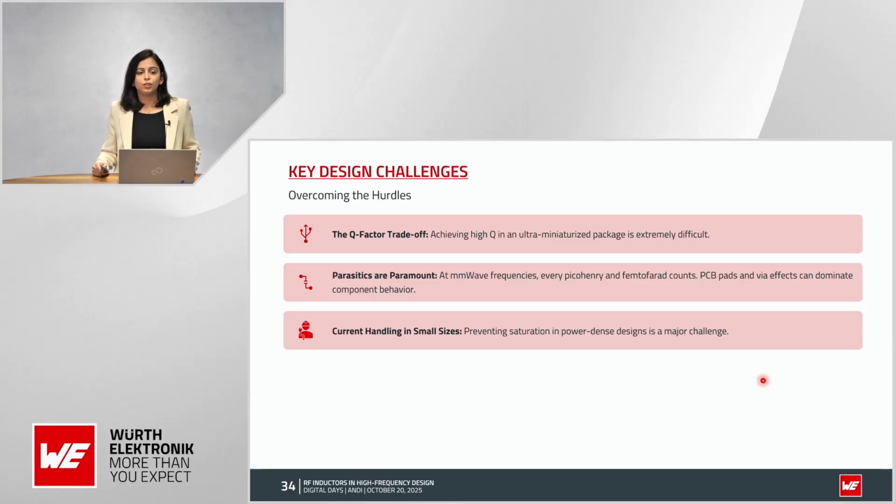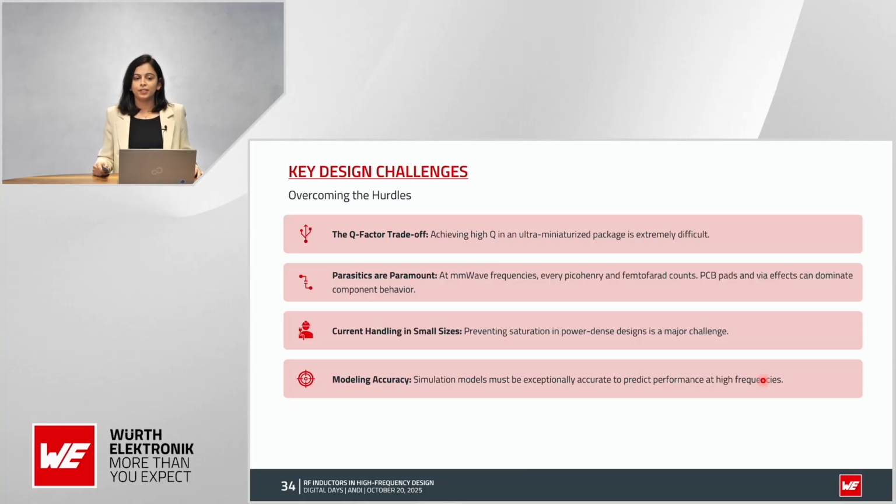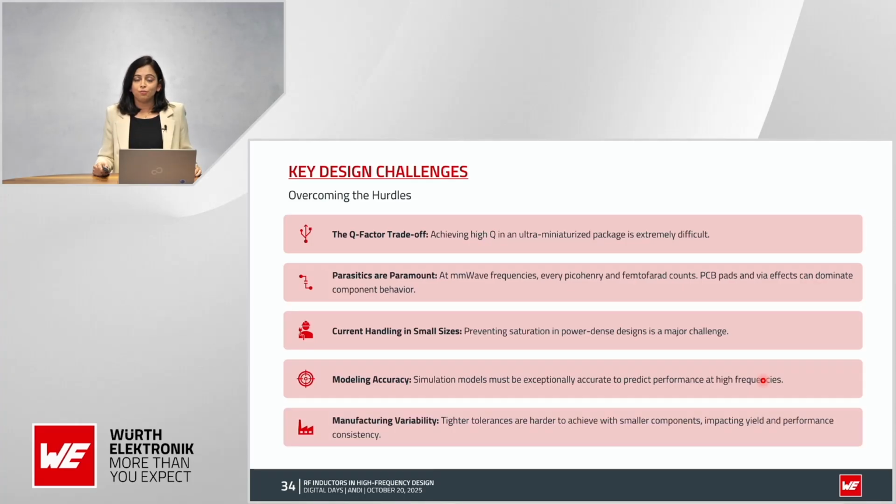Current handling in small sizes: preventing saturation in power dense designs is a major challenge. Modeling accuracy: simulation models must be exceptionally accurate to predict performance at high frequencies. Then manufacturing variability: tighter tolerances are harder to achieve with smaller components, impacting the yield and performance consistency.